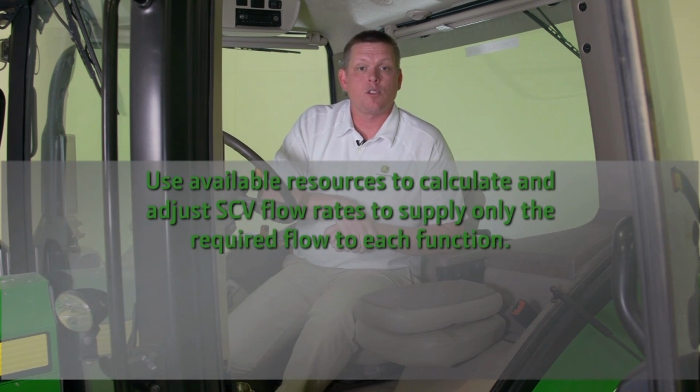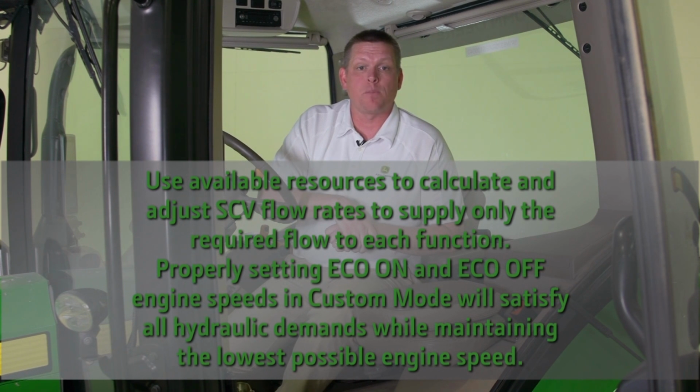Now that our initial transmission and SCV setup is complete, we're ready to go to the field to fine-tune our settings if necessary. So, by adjusting SCV flows, eco-on and eco-off engine speeds, you can satisfy all hydraulic needs and achieve maximum efficiency.